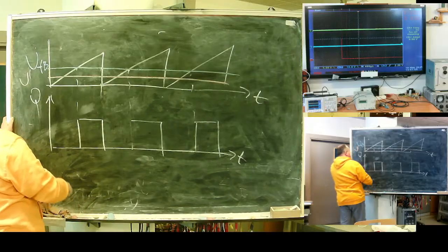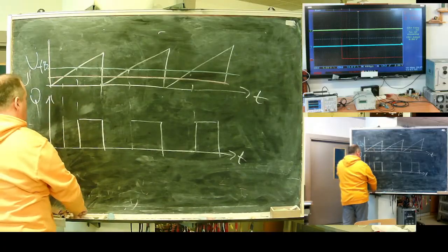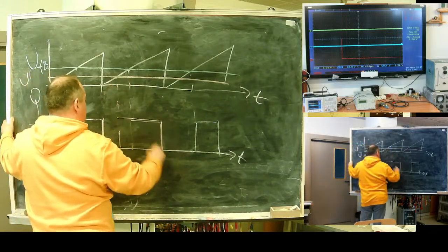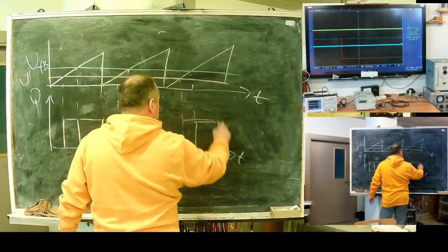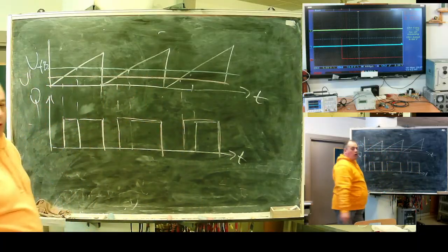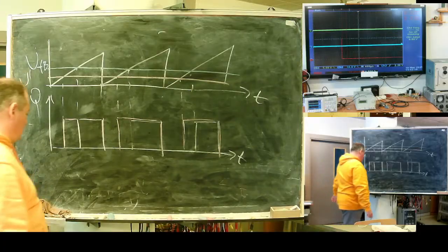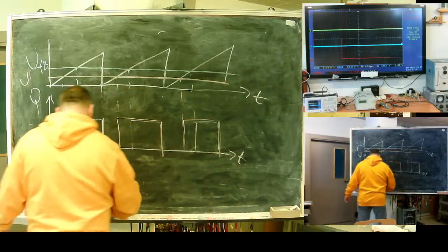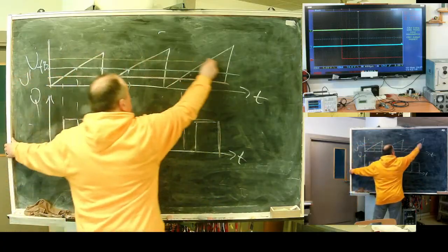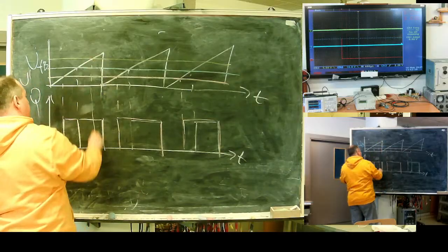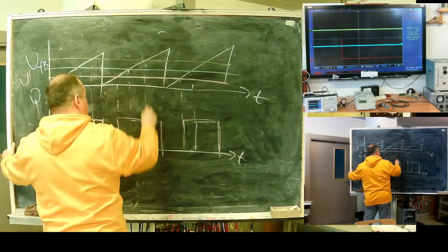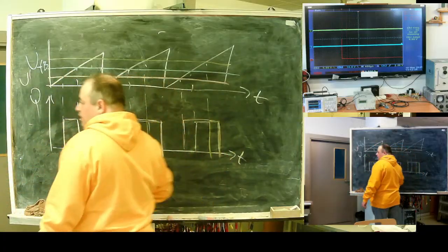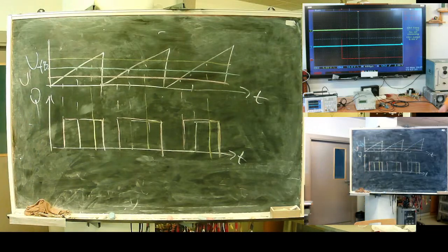Voltage decrease. Width of pulse will increase and transformer will get more energy. In another case, voltage increases, amount of energy transformer received will decrease, and voltage will go down.